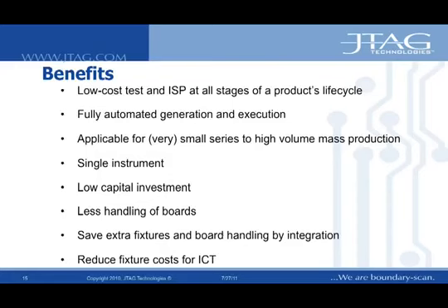R&D, manufacturing and field service all benefit from using this technology. It makes test and measurement and in-system programming on modern, very fine pitch boards possible at low cost and at all stages of a product's life cycle. A single instrument that provides the interface between the JTAG port on the target board and the PC can control the various applications we have seen before, as well as future applications, resulting in low-cost capital investments.